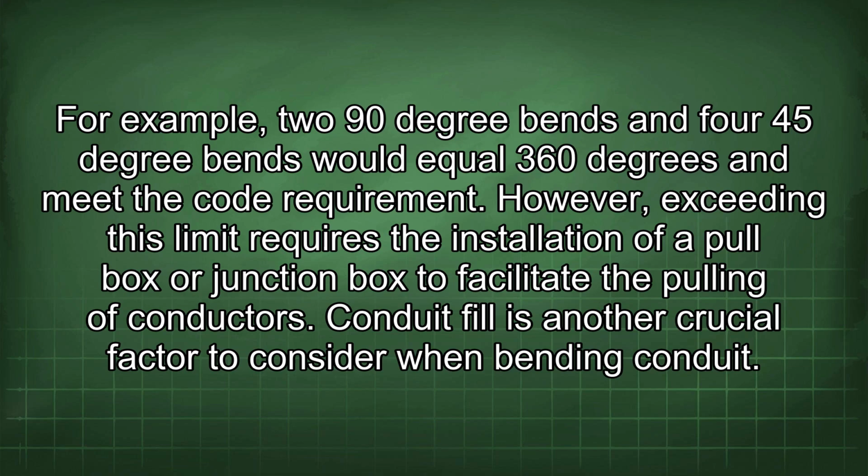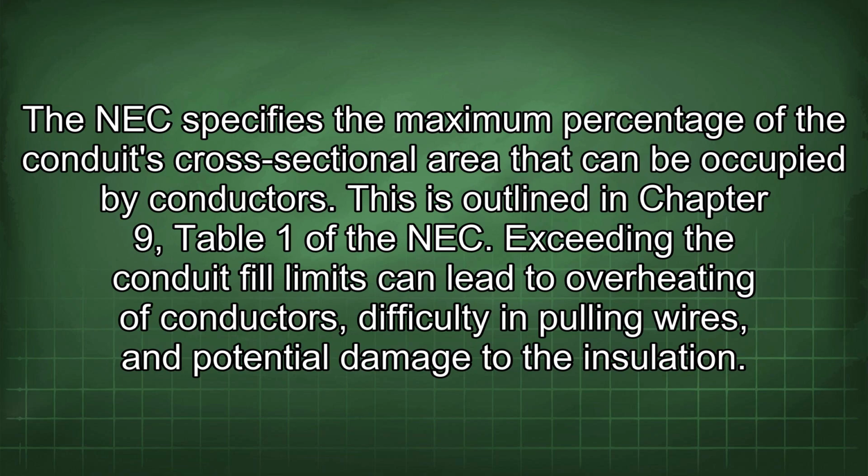Conduit fill is another crucial factor to consider when bending conduit. The NEC specifies the maximum percentage of the conduit's cross-sectional area that can be occupied by conductors. This is outlined in Chapter 9, Table 1 of the NEC.